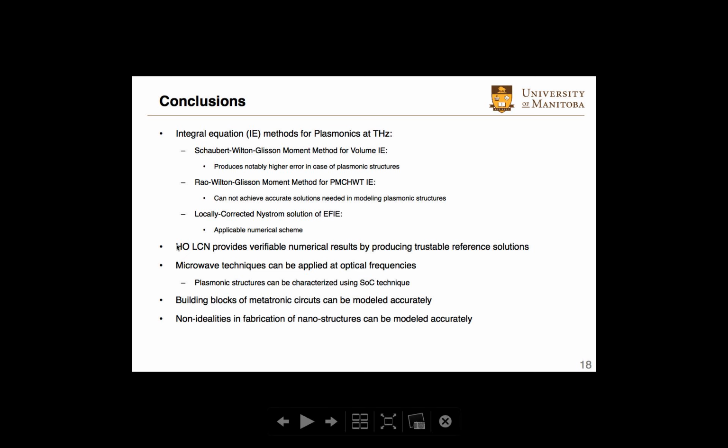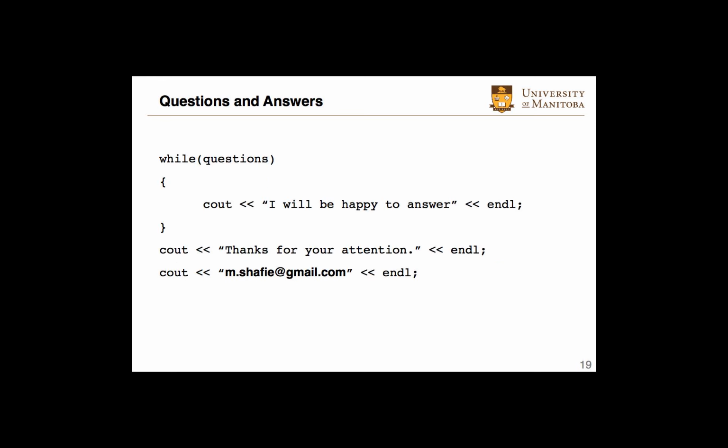And the importance of the proposed method is that it provides verifiable numerical results by producing trustable reference solutions. Therefore, microwave techniques can be applied at optical frequencies, for example, short open calibration, and building blocks of metatronic circuits can be modeled accurately, and also non-idealities in fabrication of nanostructures can be modeled accurately.